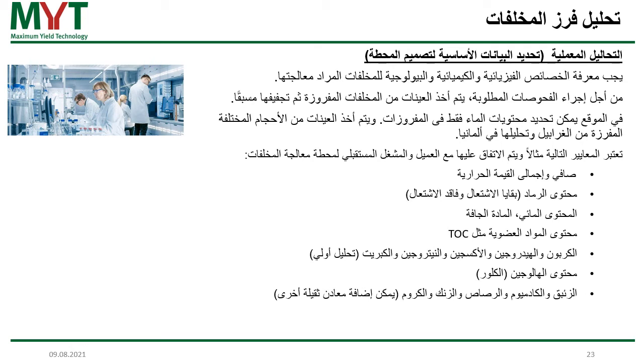You want to know the ash content, the water content, the dry matter, the organic matter, the carbon, hydrogen, oxygen, nitrogen, and sulfur analysis, which is the elementary analysis, the chlorine content, mercury, cadmium, lead, zinc, chromium, and other heavy metals, depending on what kind of sorting facility or waste treatment facility you want to establish.